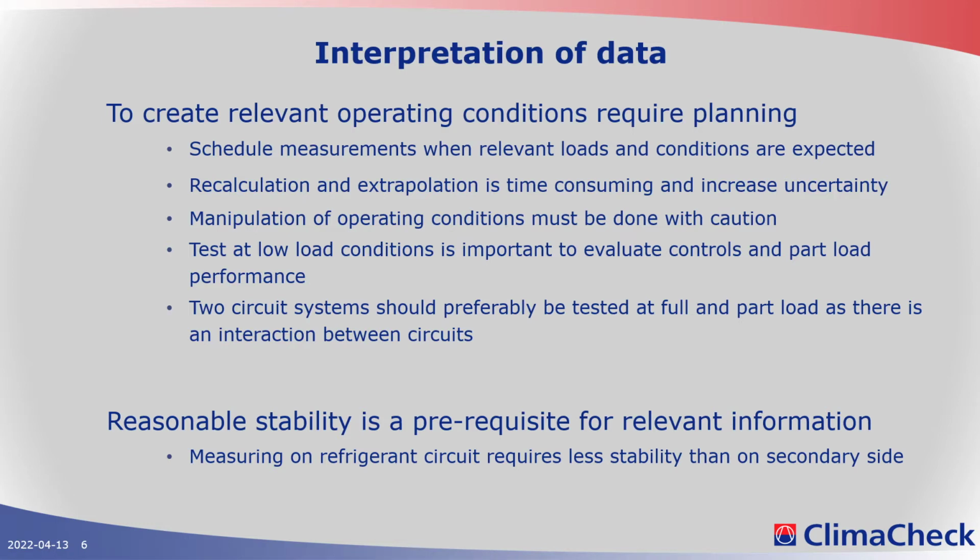And if you want to check your evaporator, condenser, compressor, and charge, if you don't know the system extremely well so you can judge based on part load, you normally need to have full load operation to be able to evaluate the system. So this, of course, needs some planning.